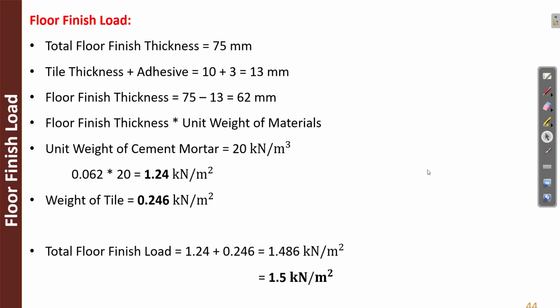So first calculation is floor finish load. Calculation of floor finish load. So assume the total floor finish thickness as 75 mm. Tile thickness plus adhesive will have 13 mm.